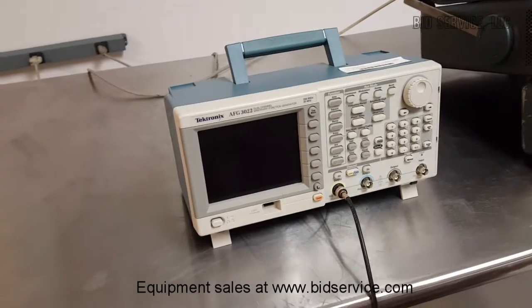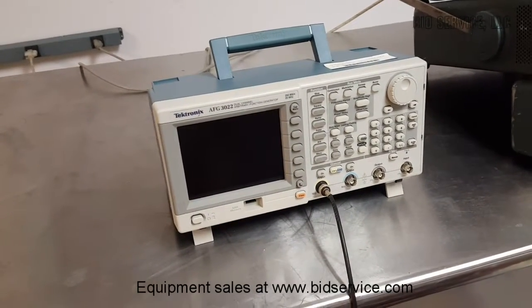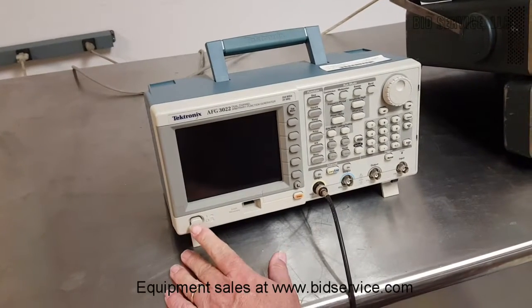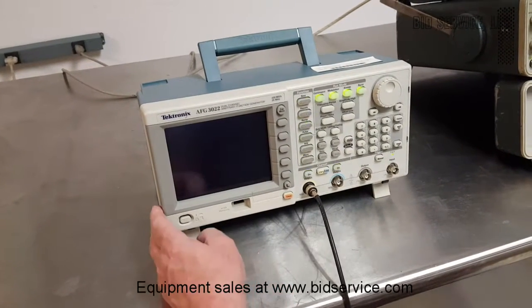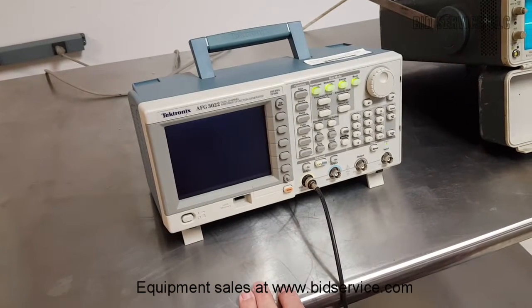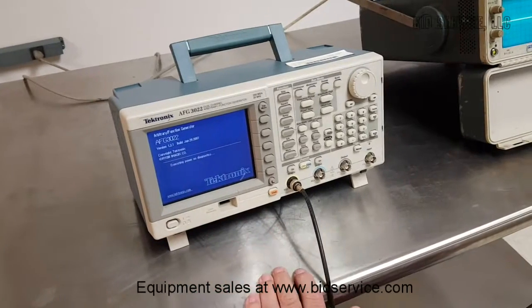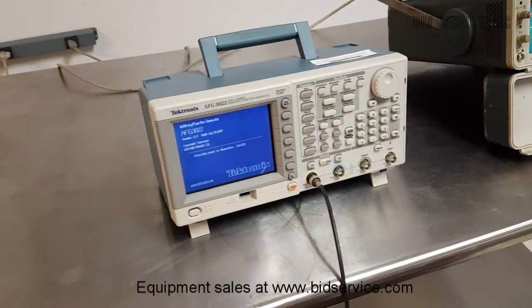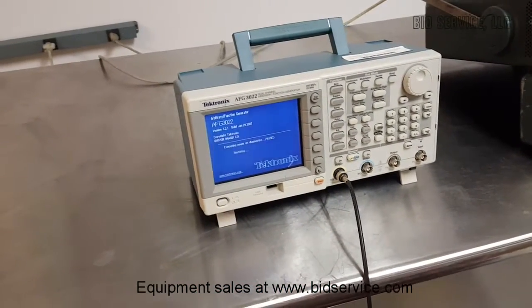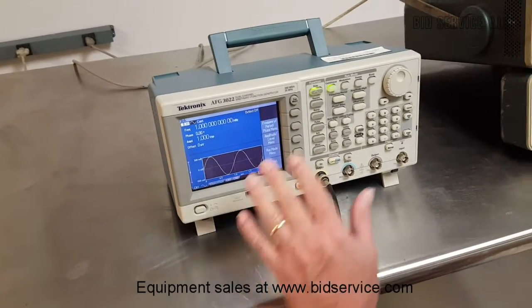The Tektronix AFG3022 arbitrary function generator. Power switch is here. This operates on 115. Power it up. And it begins its self-test, executing diagnostics. And it'll come up to the main screen here.